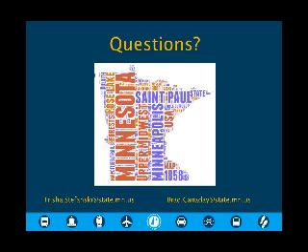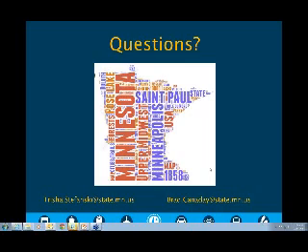I'm not familiar with change detection right now, but I see that could be an option for us in the future. We've actually done some in-house scanning with our Leica scanner, change detection on a wall. I know that they thought it was failing or moving or whatever, and so we scanned it and then we waited a couple of months and scanned it again.